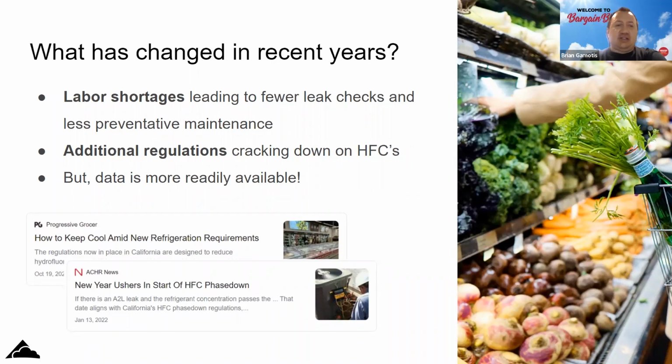It really does impact us because the techs are feeling pressured to get to the next call, especially in the summer. So sometimes that one service call would go from a 10-minute fan motor to a half an hour, 45-minute call because they're going to go ahead and do a leak check, that stuff starts to not happen as much. So it does impact us at the end user level in that regard.